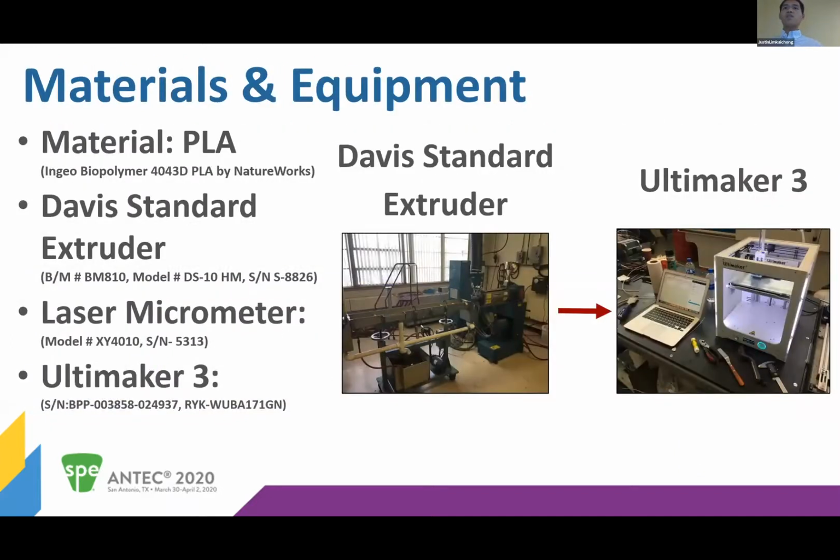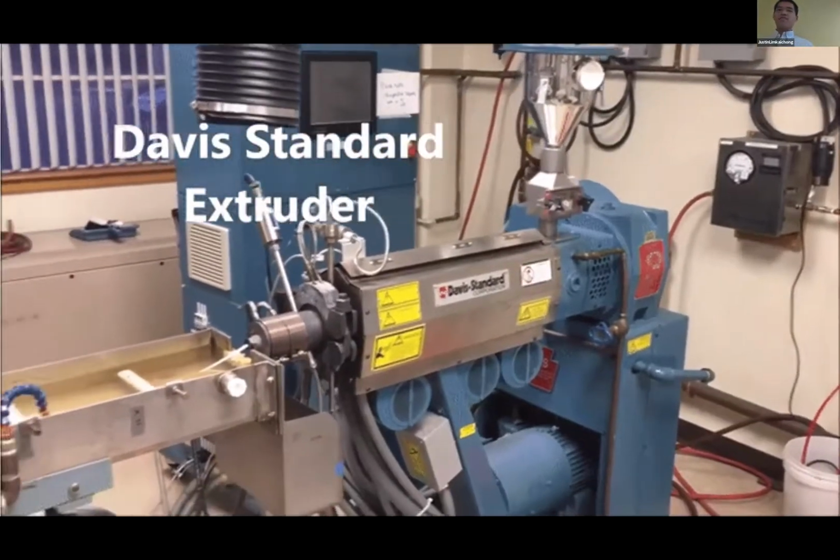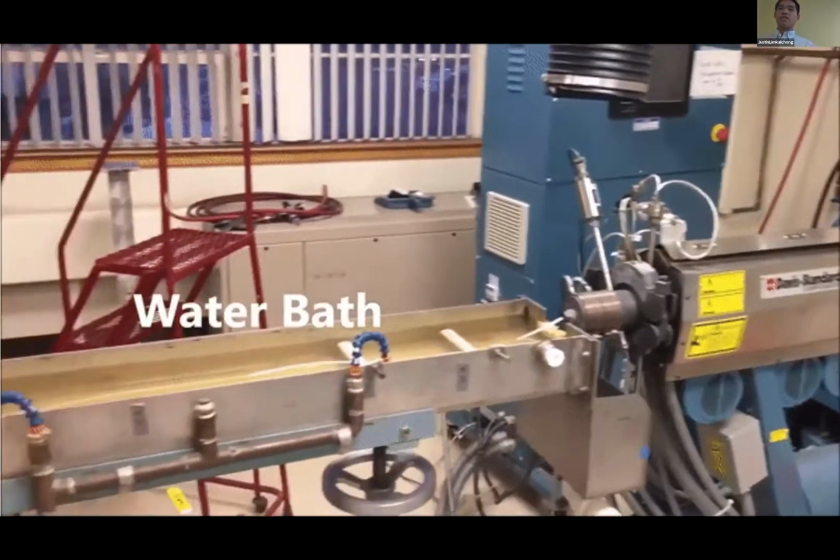So we used polylactic acid, which is one of the more common fused filament fabrication filaments that you can find in the market. Then we extruded it using a single screw Davis-Standard extruder at UMass Lowell. Then we used a laser micrometer to find its diameter. Then we printed it using an Ultimaker 3, one of the higher end or pricier fused filament fabrication printers right now.